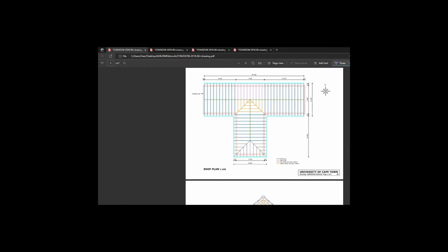So these areas are raised. They come above the roofing. The roofing does not extend over. Had the roofing extended over the brickwork, it would simply be a barge board meeting your fascia boards on the ends, or some other orientation combination. But that is the extent of where you're going to see flashing.